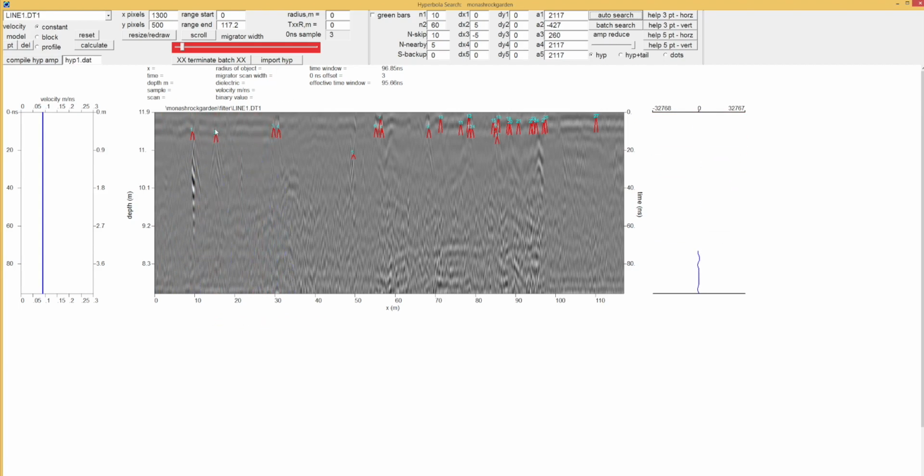So we can completely ignore all of this data, all of that data, all of this data, for instance, if you wanted to, and only take the radar traces between these and then create a depth slice out of that. And the reason for that is, in this case, obviously, I don't have rebar, so it's not a good example, but if you were doing this with rebar, you could just create a depth slice of the amplitudes of all the reflectors from each rebar, and it would give you a map showing different areas where the reflector might have a different amplitude.